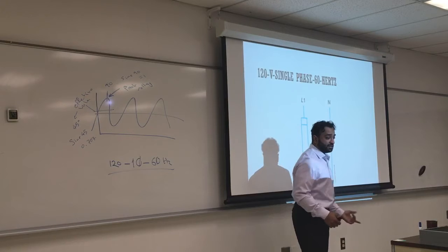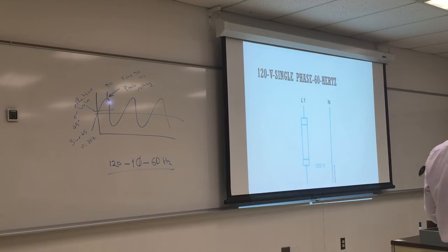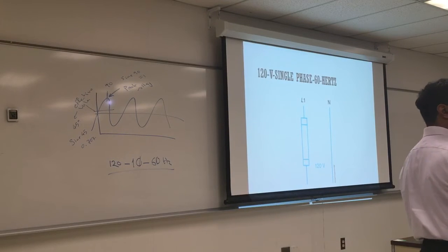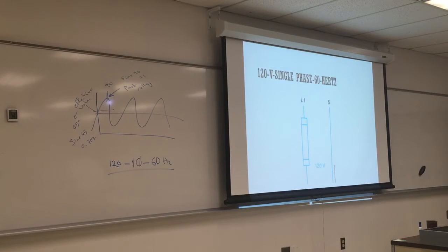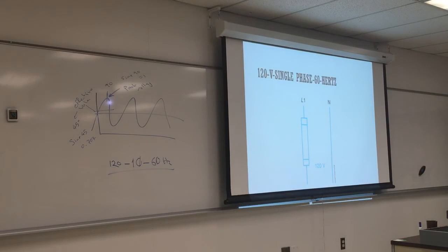This is the line voltage, as you said, one neutral and one hot. Now what is this box? A fuse or a circuit breaker? Do you put a fuse in the neutral? No. You always put it in the power source. If you go and see a small power switch or circuit breaker, it will look like these things.